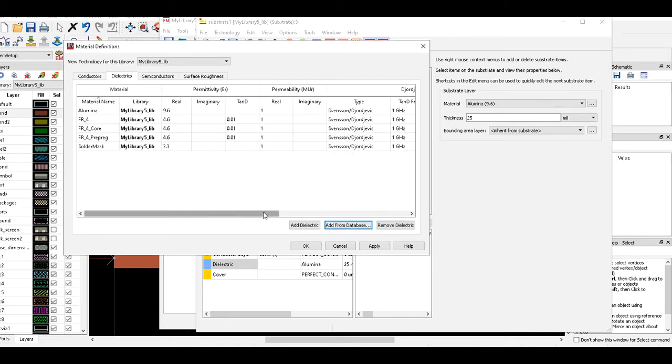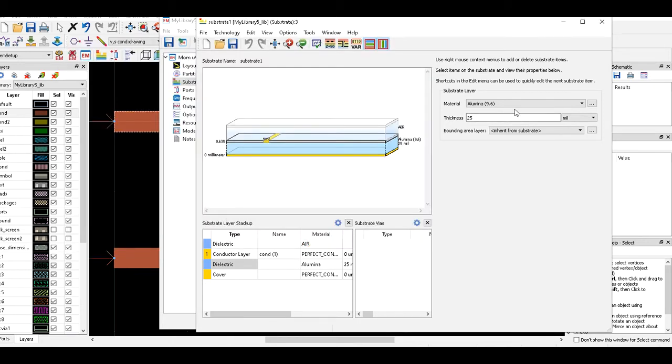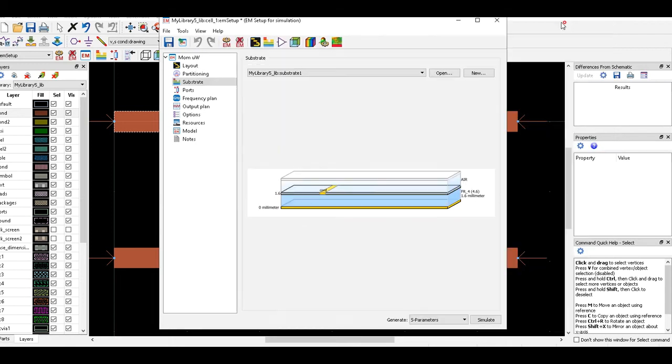It's now added there. We click OK here. We can now go back and select our FR4, which has the dielectric constant of 4.6. I will change here to mm and use 1.6, which we use for our design. After we change this, we leave everything else the way it is. Just click save. You see that I've saved that, and it's automatically reflected here, telling us that it is now defined.